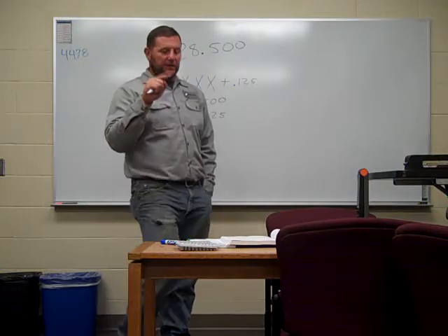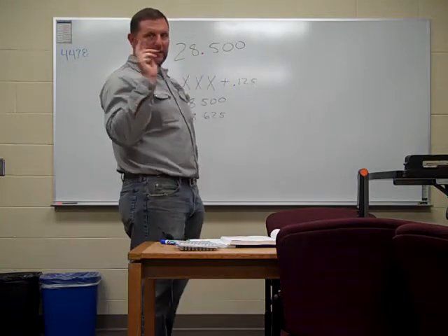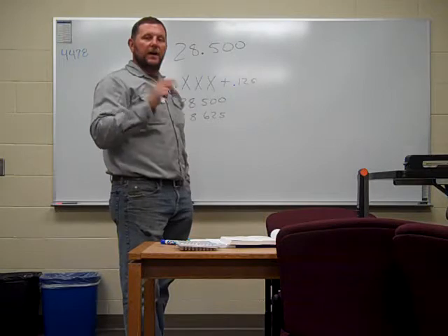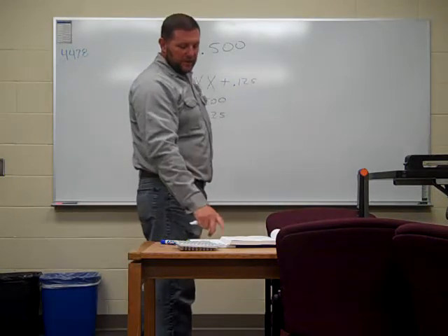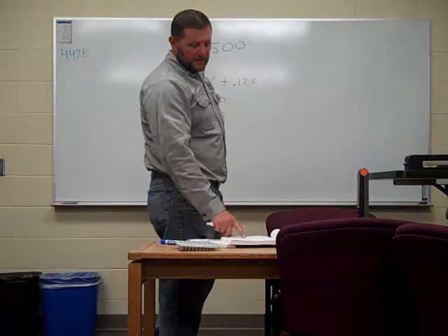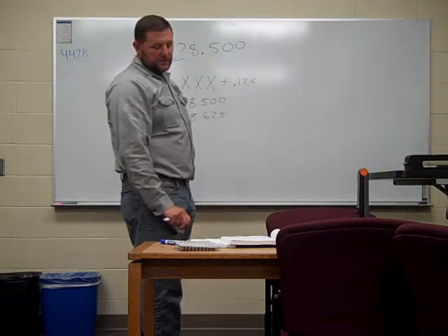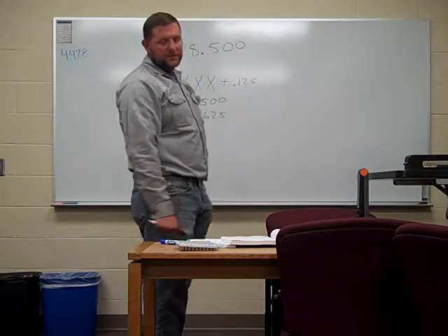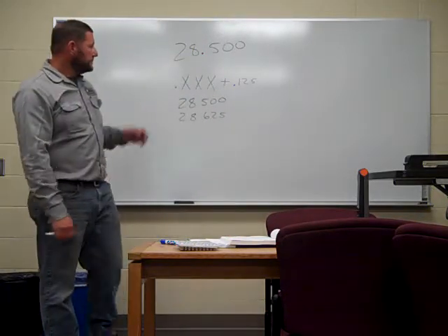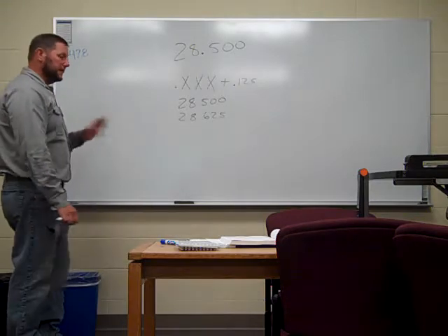Go in there. Look at the number of X's. That applies to that many decimal places on that print, or whatever dimension it may be. And as you go through there, it'll give you fractional and angular. As you look, it says plus or minus 1/8 for fractional, angular plus or minus 2 degrees. Be sure you go through there and apply those.